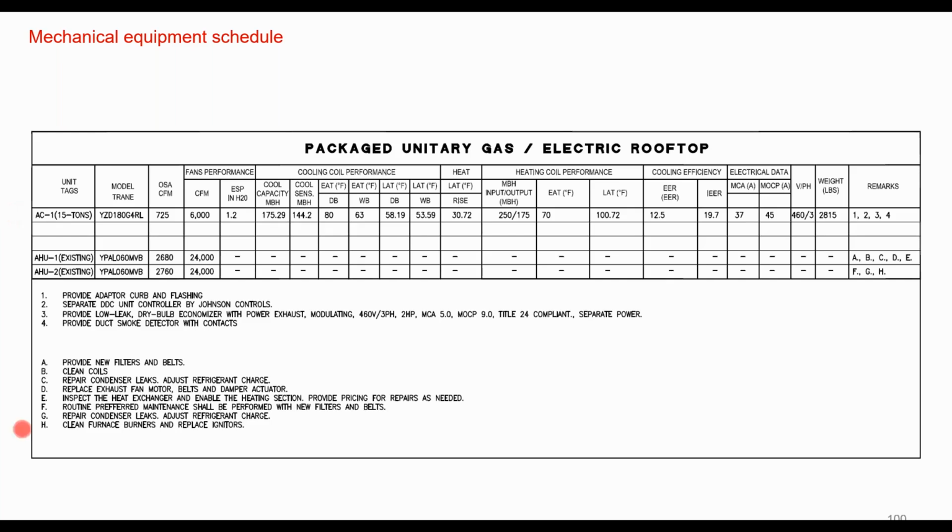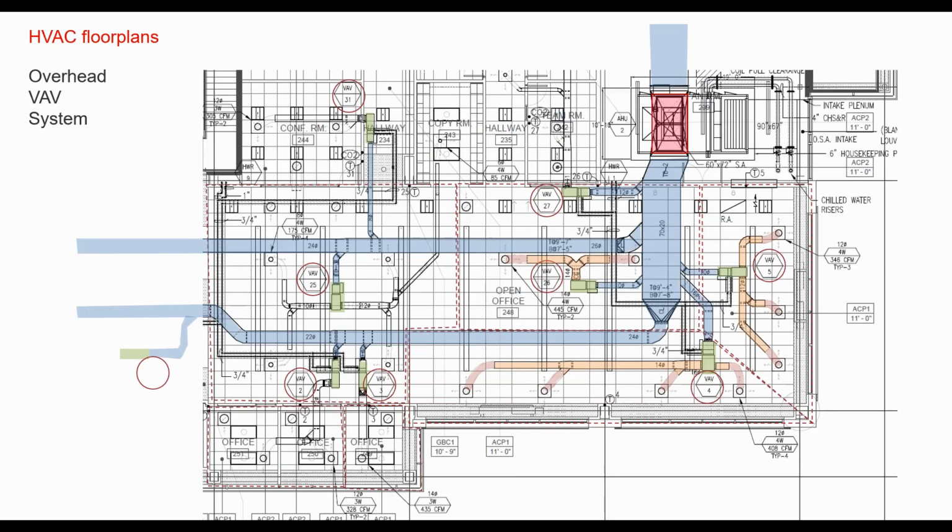For the building performance factor, yeah. So your exhaust fan energy still ends up in there if it's part of your package system. Appendix G is part of 90.1 and not Title 24. Title 24 has a slightly separate approach for dealing with fan power, but they still will have you account for that exhaust in your total fan system performance.